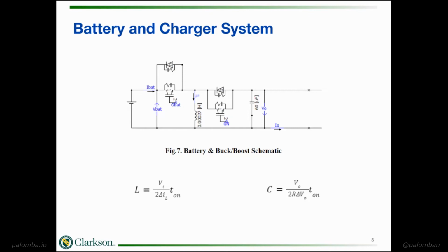And as such, we also designed the battery input to be 1,104 volts. So that comes out to 23 battery modules in series and 92 strings in parallel. So we had a lot of batteries in the system, over 2,000.